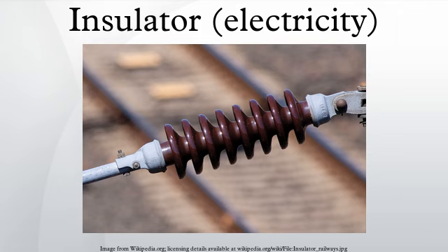Class 2 insulation means that the device is double insulated. This is used on some appliances such as electric shavers, hair dryers and portable power tools. Double insulation requires that the devices have both basic and supplementary insulation, each of which is sufficient to prevent electric shock. All internal electrically energized components are totally enclosed within an insulated body that prevents any contact with live parts. In the EU, double insulated appliances all are marked with a symbol of two squares, one inside the other.